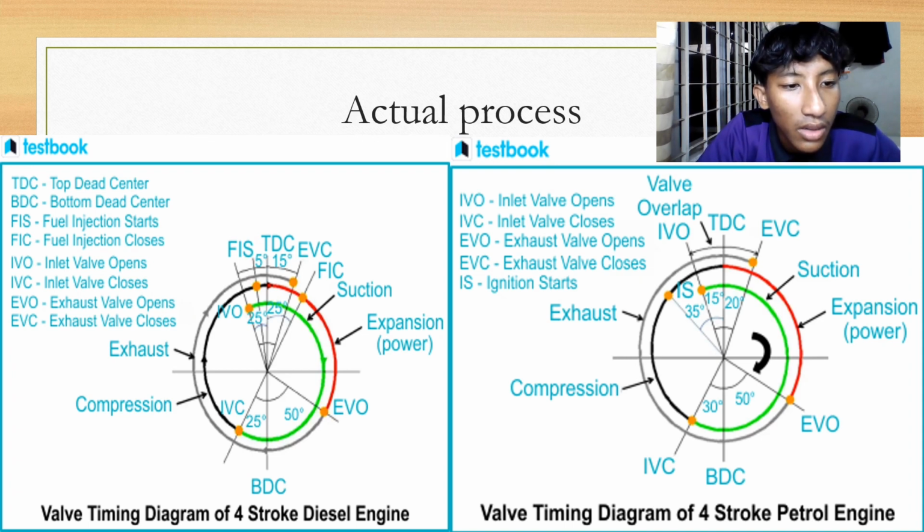To begin the exhaust stroke, the exhaust valve opens approximately 30 to 50 degrees before BDC. This enables the expulsion of the combustion residuals as the piston moves from BDC to the TDC. The exhaust stroke continues until roughly 10 to 20 degrees after the piston reaches TDC.